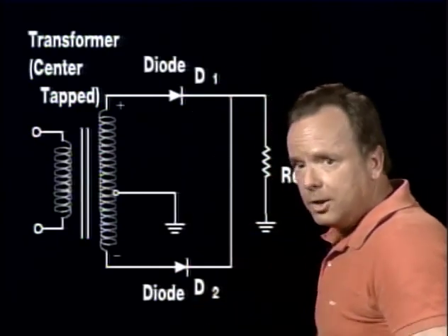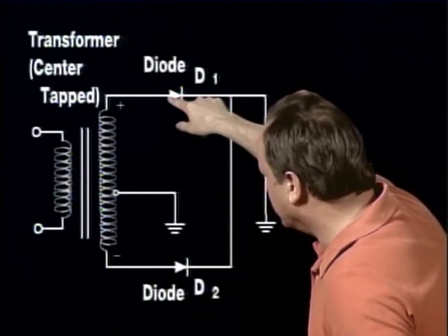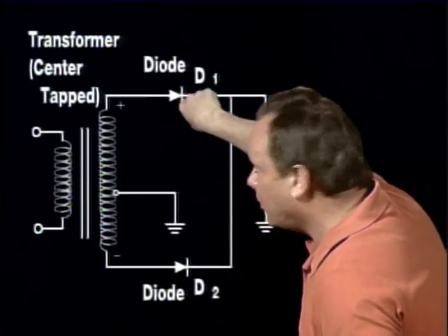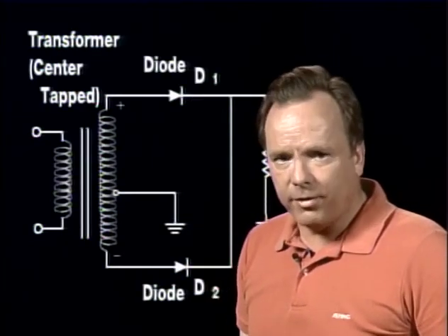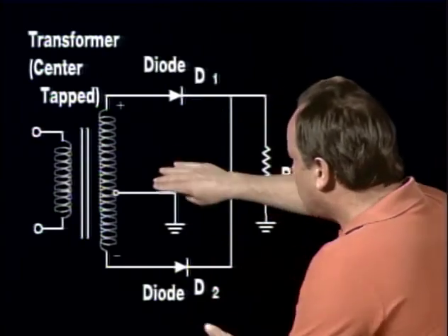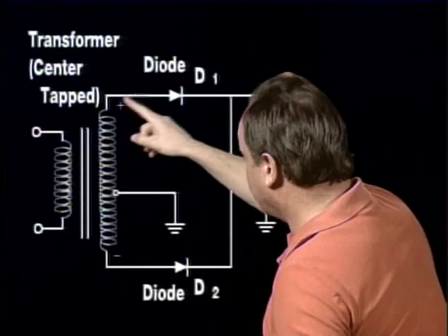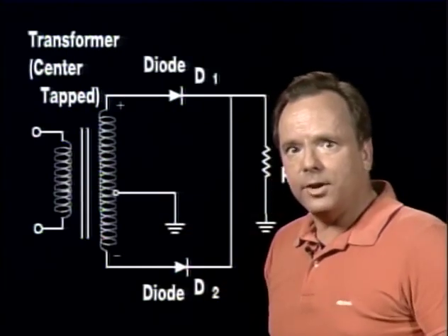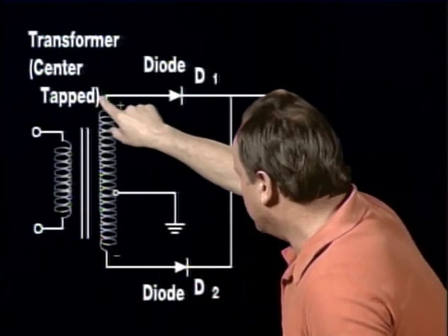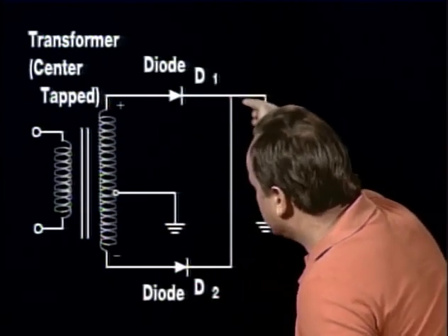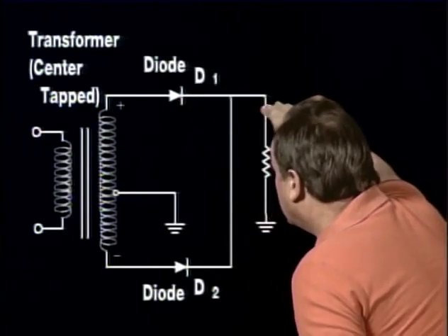A diode can either be a tube or a transistor, and this is a symbol for a transistor diode like so. Now a diode you can think of as a check valve, and they're used in rectifiers. Now a rectifier is a circuit that converts alternating current, which reverses itself periodically, to direct current. You can see how it would work. If you have alternating current that's reversing itself, this diode lets the current go this direction, but not that direction. So what you have now is intermittent direct current.